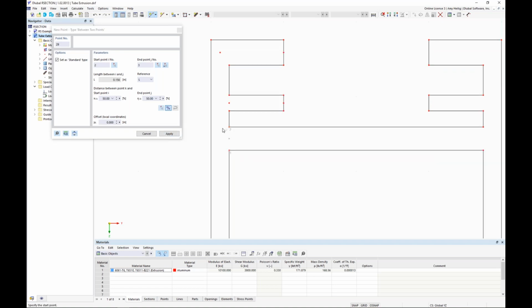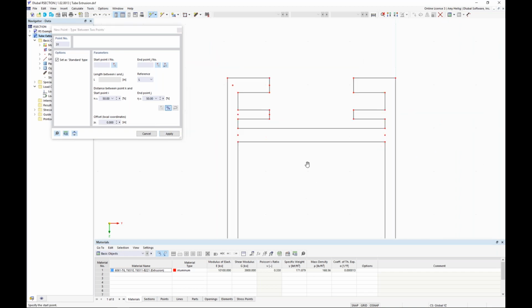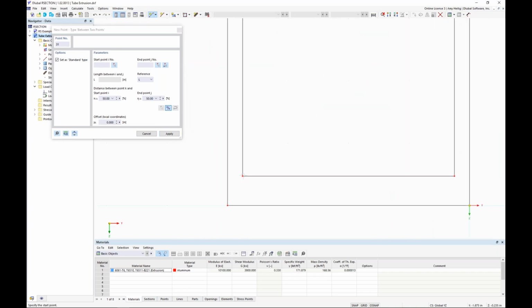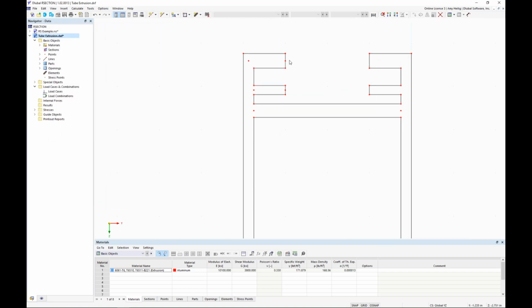We'll do so at this 3rd horizontal location as well as on the right side here. So clicking my 1st point, my 2nd point, and finally we have a couple points down here at the lower left that we would also like to generate. So once we have completed the generation of the nodes, now notice I'm not creating these same nodes on the right-hand side. We'll be able to mirror our elements from the left to the right-hand side to save us a bit of time. I'm going to hold down my control key to select both of these center nodes